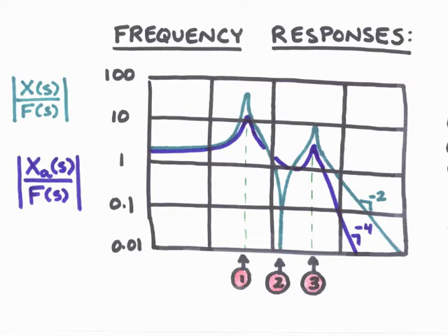So you'll note the following important fact about the dynamic vibration absorber. It only reduces the vibration over a very small interval of frequencies. And this is why it's important to use a dynamic vibration absorber on a system that will tend to be rotating at only one speed. Perhaps it's 3600 RPM, which corresponds to a 60 Hz excitation in the motor coils. The dynamic vibration absorber cannot reduce the vibration response across a wide range of frequencies. It's strictly a narrow band device.